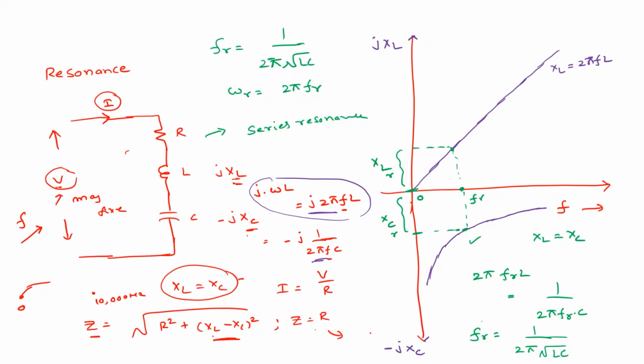Okay, so now the question: from 0, some frequency is there, for example, it is operating. So 0 less than f less than f_r. What kind of circuit is it? Is it an inductive circuit or a capacitive circuit? What is the circuit behavior from 0 to f_r? Capacitive, yeah, good. So why is it capacitive from 0 to f_r? So this is the range, 0 to f_r.